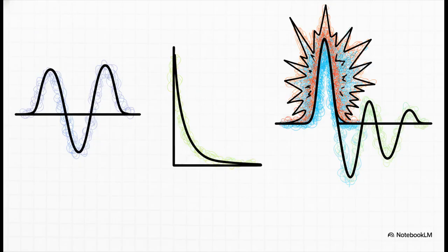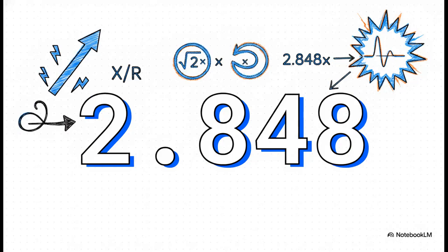Let's look a little closer at that current doubling effect. In differential equations involving resistance and inductance, a DC component naturally accompanies the symmetrical AC component. The magnitude of this DC component is also determined by XD double prime. But how long does it actually last? Well, its decay is governed by the armature time constant TA. This time constant is a direct function of the subtransient reactance and the armature winding resistance. If your generator has a high XD double prime and very low armature resistance, watch out. That DC component is going to hang around, creating a massive, sustained current spike.